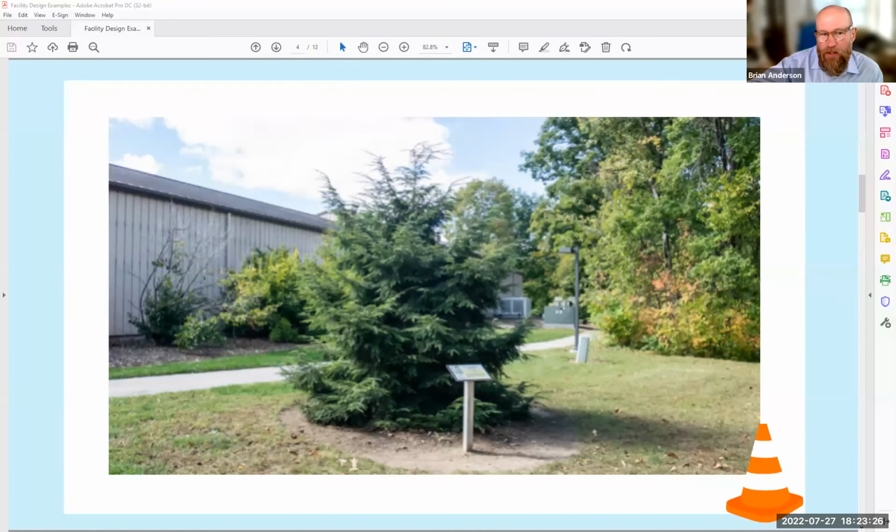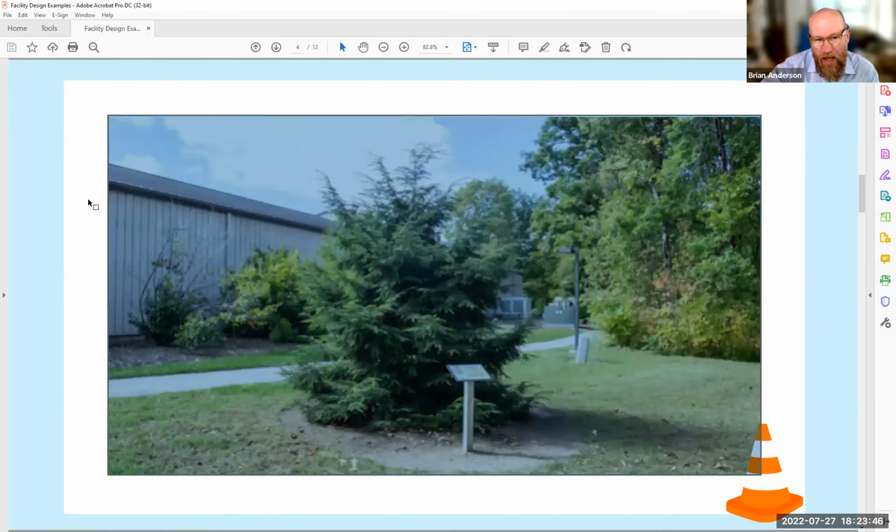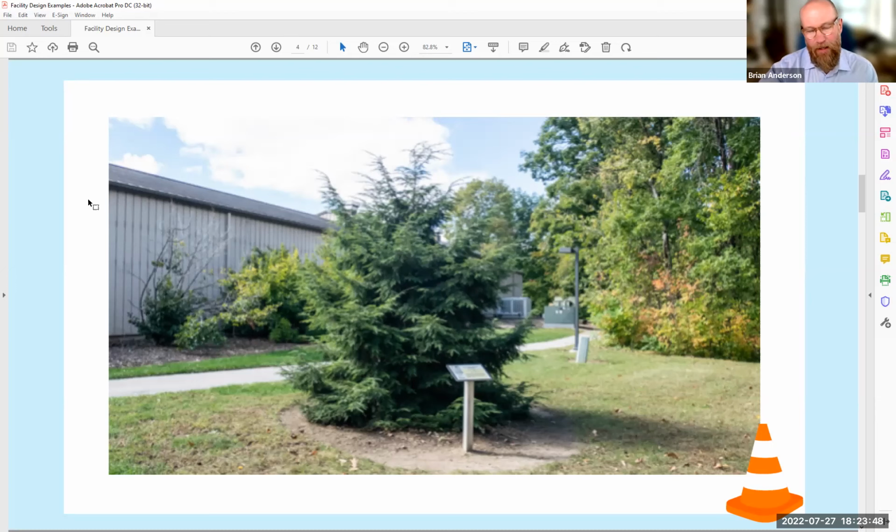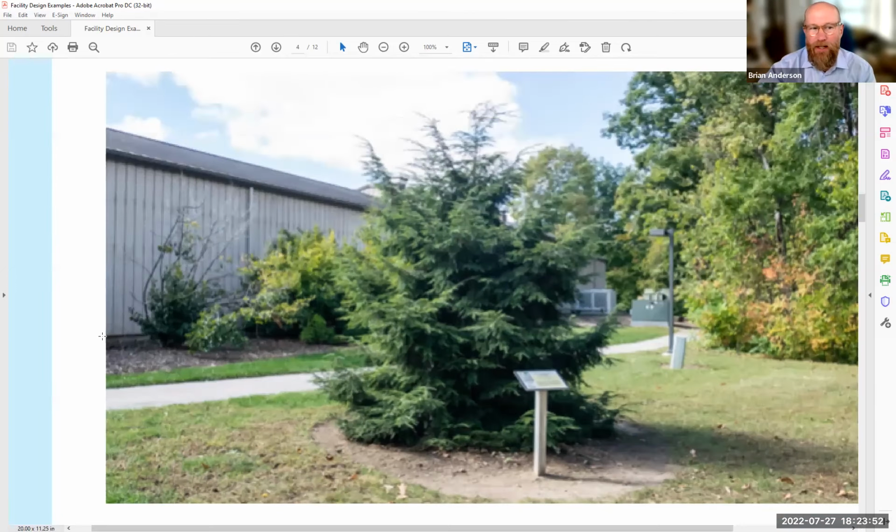So if you had a good 6-foot buffer and, as we mentioned earlier, positive slope away from your building, one of the things to my eyes as an architect, I can see that that's basically what we call a PEMB in the background, a pre-engineered metal building. I can see that because of the roof slope. I can see it because of the detail at the eave, the type of gutter line that's coming down. And if you look down behind the landscaping on the left-hand side, you'll see a little bit of exposed concrete, and you can see the siding hanging out over that.